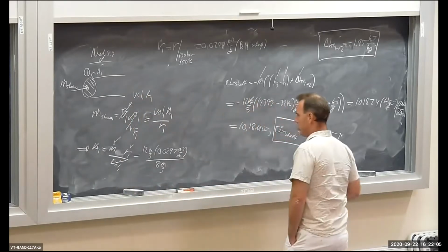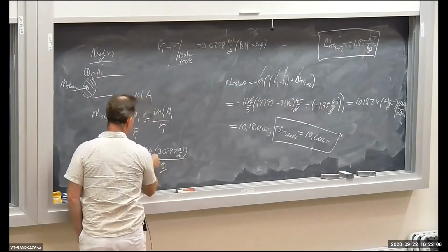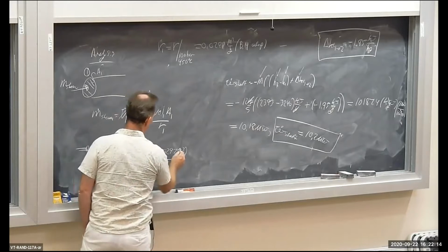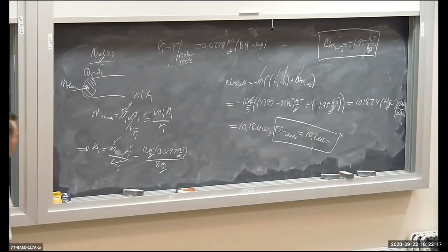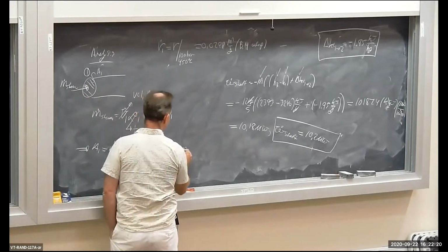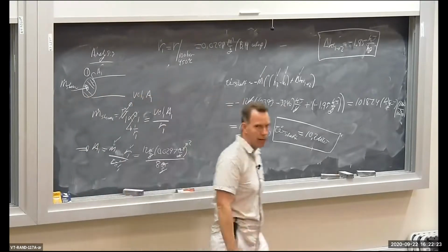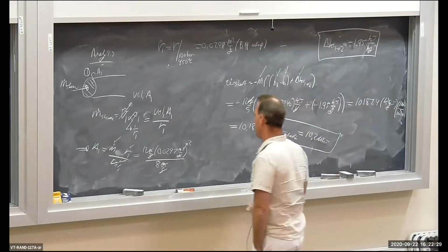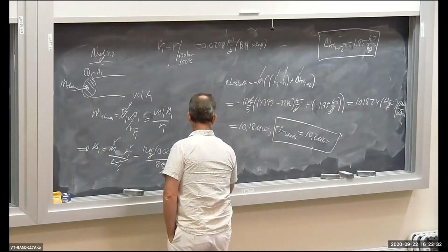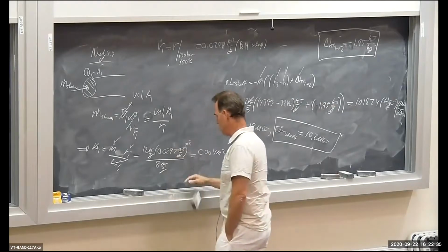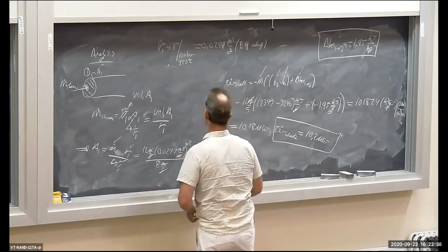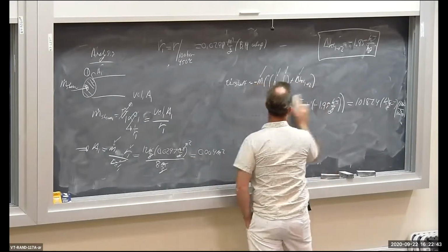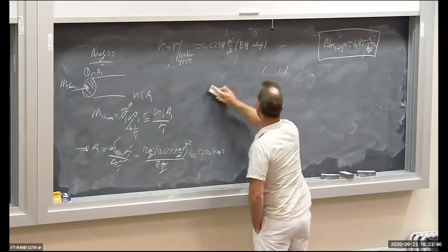Let's look at the units here. The seconds cancel out, meters per second and kilograms per second, that's gone. The kilogram cancels out in the mass flow and the specific volume. And one of the meters cancels out in my cubic meter per kilogram, and I get meters squared. The result is 0.004 square meters. So the inlet flow area is 0.004 square meters.